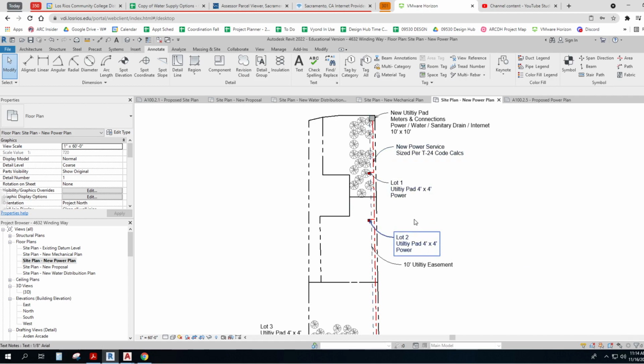But I've chosen to just take what's called an easement in the back. Now, that doesn't mean you can't plant things and have nice things back here. But if anybody ever needs to do work, they get to just come back here in this 10-foot wide strip. And I made it 10-foot wide. It could be 8, it could be 6, it could be 4. But that's just an area that you must give access to any utility worker.